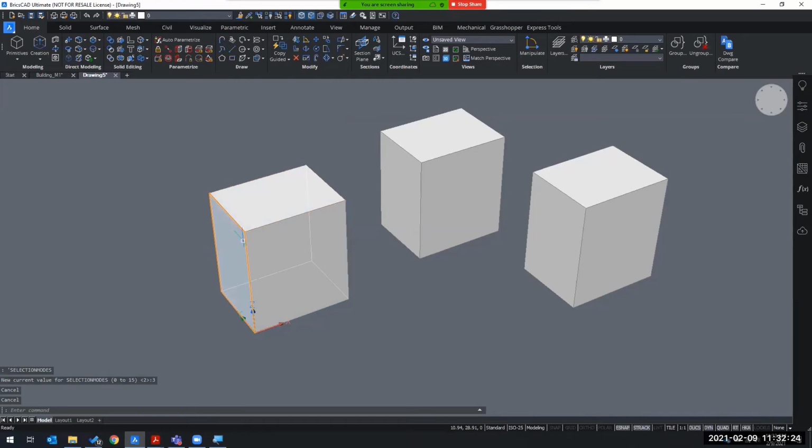So you can toggle through your selection with the control key. It's the same thing if I were to have only solid now. Instead of giving priority to the solid, I can temporarily give priority to a face by pressing control. So now I get to click the face.